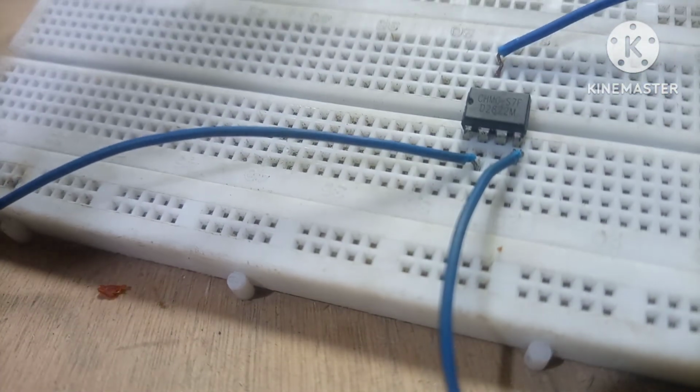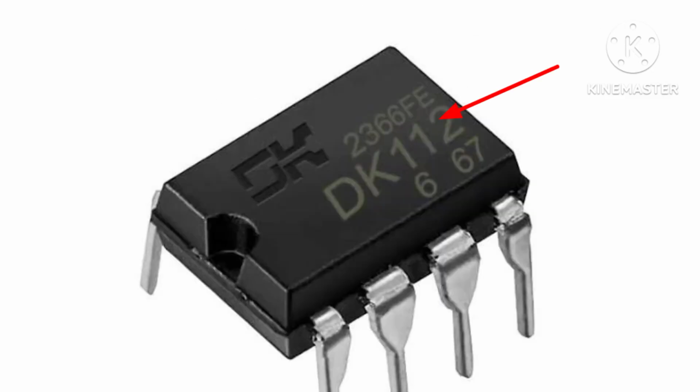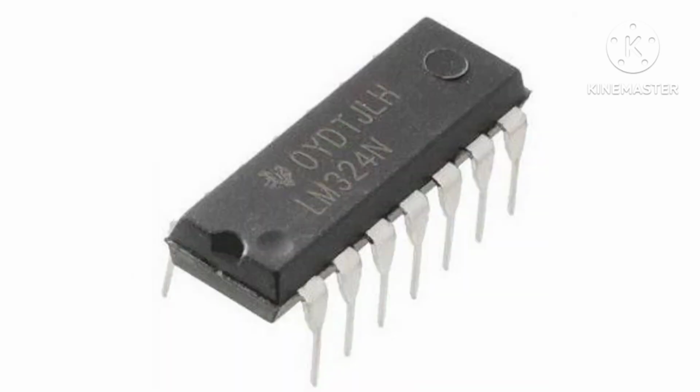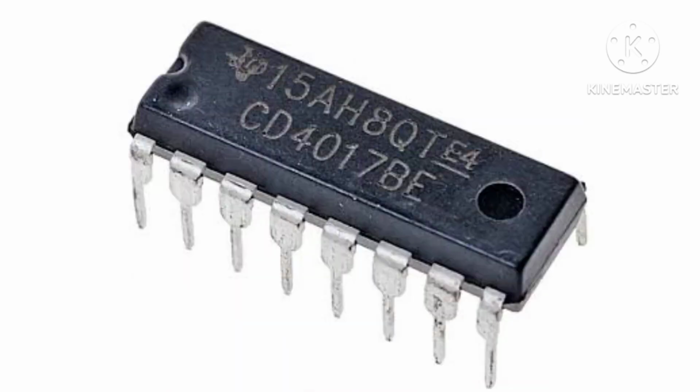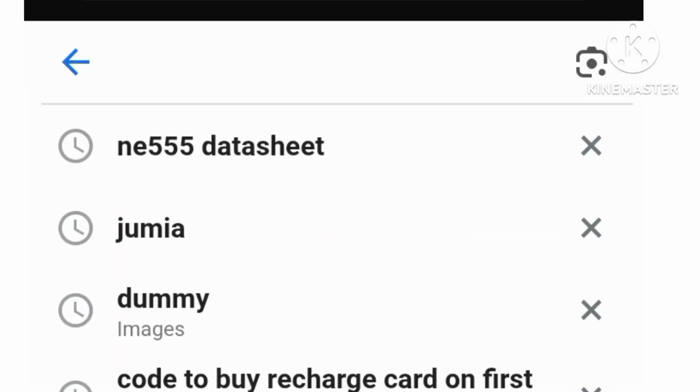Step 2. The IC code. Every IC has a code printed on top of it. Something like NE555, LM324, CD4017, or maybe something less familiar like UC3842. To make use of a random IC, just type the code into Google and add the word datasheet.